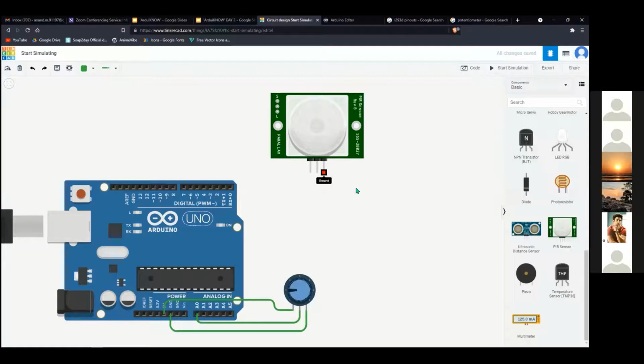Okay. So again, we'll do a quick recap. Based on the signal, in order to measure it, I will connect to pin number 2. Since the sensor output is digital, I can use any of the digital IOs that are available in the Arduino.